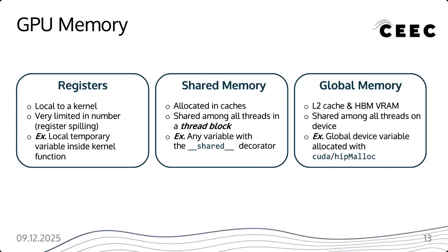We allocate memory in the VRAM with commands from the CPU. And of course, just like with any compute architecture in existence, the closer you get to the compute circuitry, the faster the memory fetching is, right? So obviously you want as much of your important data in the registers as you can without overusing the registers. And we could prefetch memory into shared memory to make this fetching of that faster later when we do our actual computations. And obviously, if we have to go all the way to global memory to get something, that's going to be a slow operation.